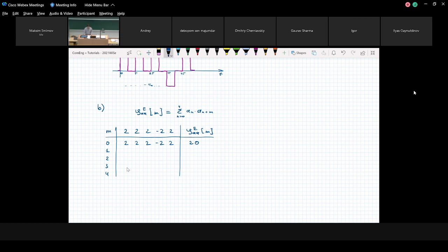Then when we shift by 1, we shift it to the left. Because it's a finite sequence, if we shift it and have nothing, we just place 0 instead of the element. Calculate this element-wise product and sum. The result will be 0 because we have 8 minus 8, 0. And I shift this sequence by another index.